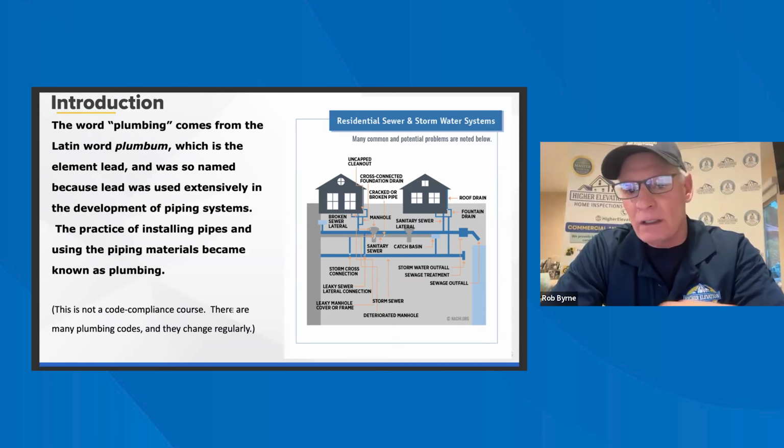most jurisdictions, and we're not code, but basically it says if the operation of a dryer can affect the operation of an appliance, you're required to have outside combustion air. The furnace has its own combustion air. The water heater does not. So I would write this up as a defect that we don't have outside combustion air because we are so close to the dryer. So whenever the dryer, whether it's gas or electric, is on, it pulls oxygen through the house. We don't want it to pull oxygen containing exhaust gases from the water heater. So the issue I see here is lack of outside combustion air for the water heater.